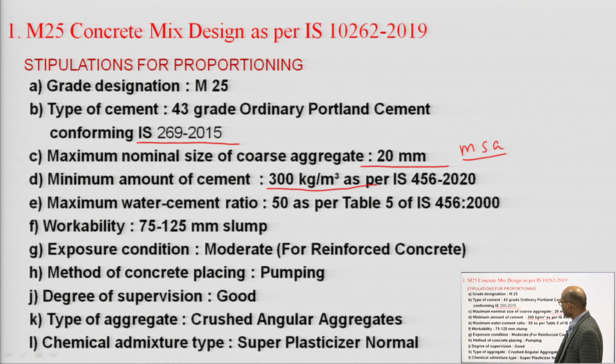Okay. Next is the maximum water cement ratio. This you can find in IS 456 table number 5, based on durability requirement and exposure condition.